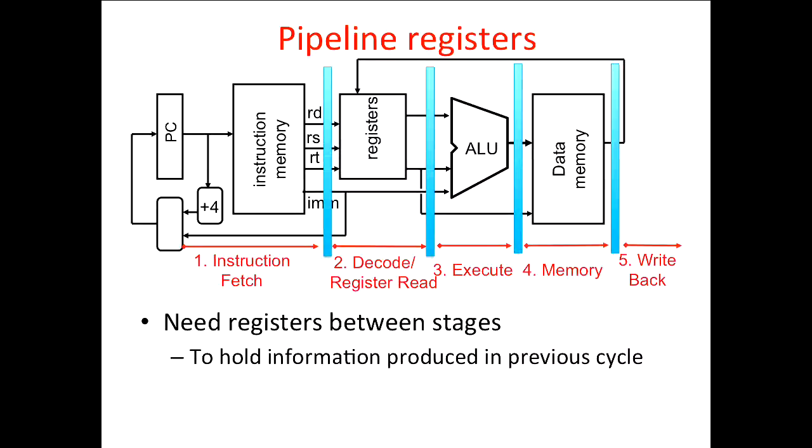And the next clock cycle, we'll start a second instruction, reading the program counter, fetching instructions, while this guy moves on through decode. So just as with the laundry example, we're not going to wait from start to beginning of each instruction. We're going to overlap them. So when the pipeline is full up, we're going to have, in this case, 5 different instructions at 5 different places in the process of the pipeline, right? And this will give us a maximum speed up factor of 5.